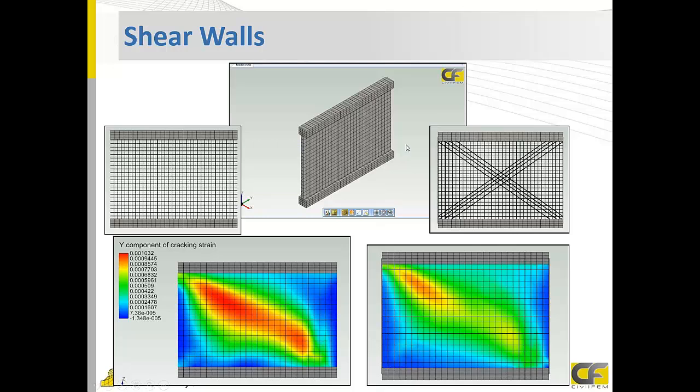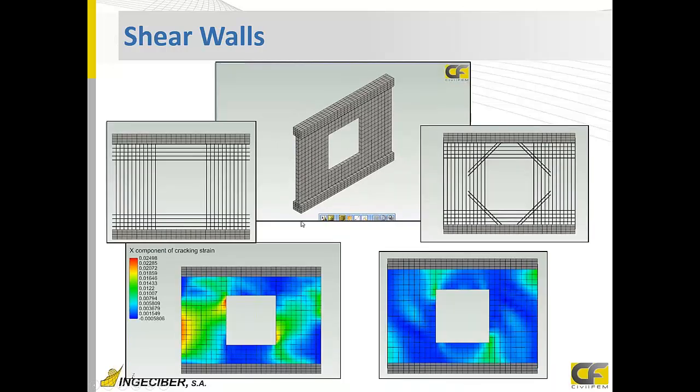If we perform a pushover analysis in this wall with horizontal load, also adding the vertical pressure of the building, we can perform different pushover analyses at different levels and improve this reinforcement. Also, we can check different reinforcement configurations for these other holes and these other walls, in case we have windows or...